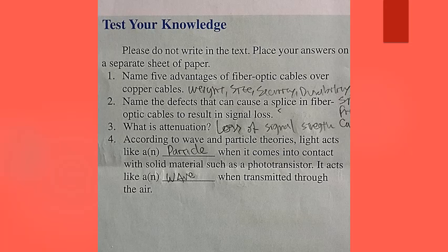There are more summary statements. Attenuation is the signal loss in the fiber optic cable. It is measured in decibels. Scattering is the loss of signal due to impurities in the core material. Dispersion is the distortion of the signal caused by the light waves arriving at the receiver at different times. The Fresnel loss is caused by differences in light refraction between different materials.